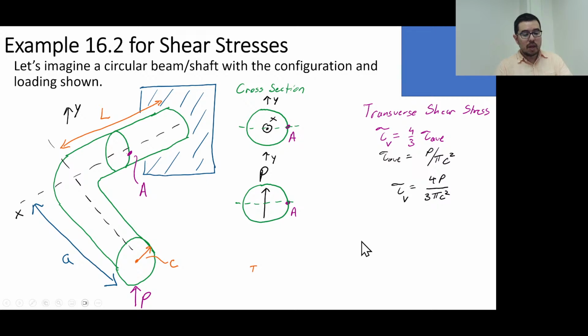And we've got shear stress from the torsion. So this is how we think of this one. This torque is coming around here. The shear stress from the torque is going to be max at the outskirts. So that's going to be a TC over J quantity, right? So this tau T, we'll call it from the torque, is TC over J, and it's acting in the same direction as the P, as I've drawn here.